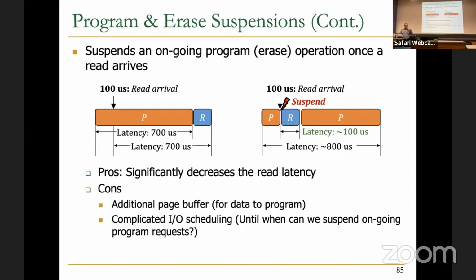Like you cannot really suspend program all the time. At some point, your program needs to be done, essentially. So there should be some intelligent control to realize until when we can suspend it. And also it has a negative impact on the endurance, which is another issue. Whenever you suspend and repeat this, and then when you want to resume it, this process can make the endurance worse, essentially. People have observed that. Question?